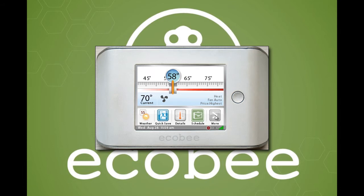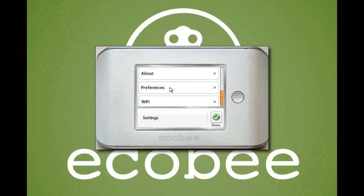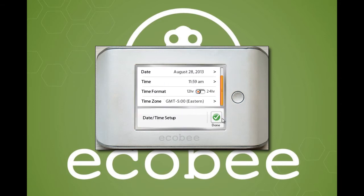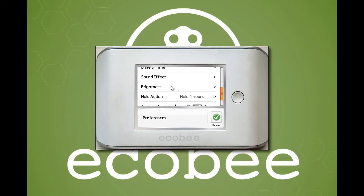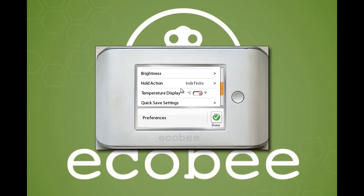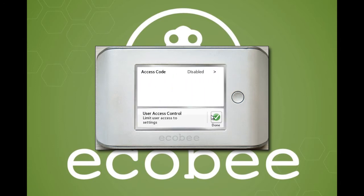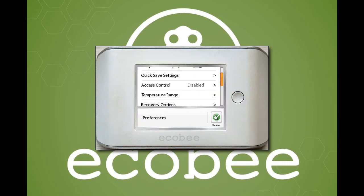To access further settings within the thermostat, tap on the More icon. This will provide another screen with further options to select. For example, by tapping on Preferences, I can give the thermostat a unique name, change date and time, choose my active and standby brightness, select the type of hold action, adjust available temperature range when in heat and cool mode, or choose to restrict access to the device by enabling a passcode. All of these user preferences can be adjusted or changed from the personal web portal.